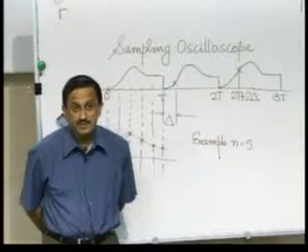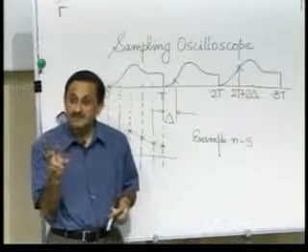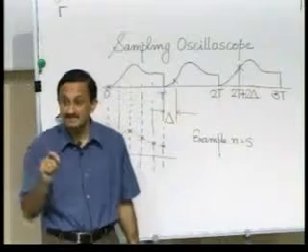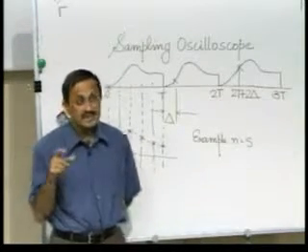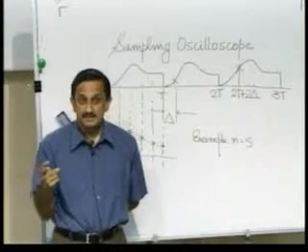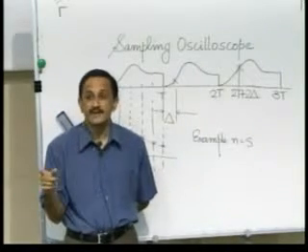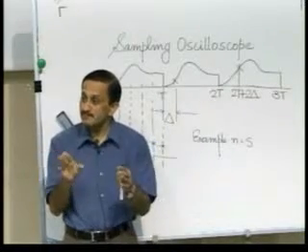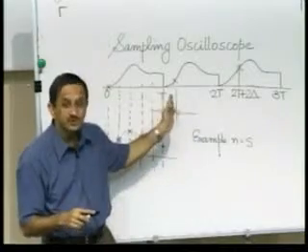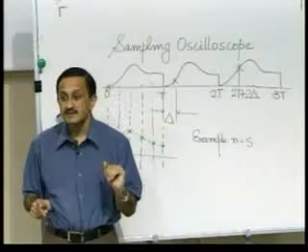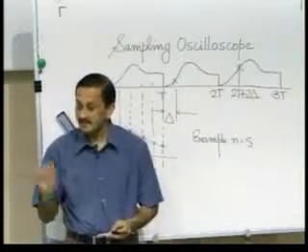Yes. Now, in fact, it is also important to know a priori about the possible frequency, or it also means that there is some prior adjustment that needs to be done before a satisfactory display is obtained, right. See, the sampling interval is in your hand, but matching the sampling interval to the waveform that is coming in needs adjustment. So, in fact, you have to allow flexibility in the sampling interval here, because without that you will not be able to match the frequency that you are trying to display and the sampling interval, right. You can see that the ratio needs to be rational. The sampling interval divided by the sampling period needs to be a rational number here, right. That is the most general requirement, and that needs to be done by adjustment.